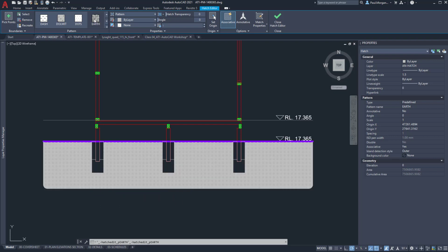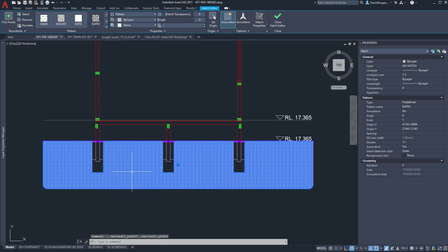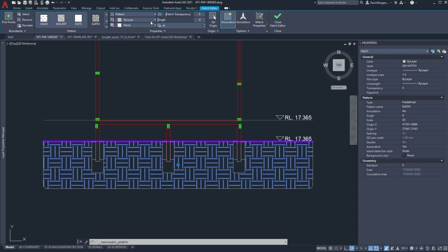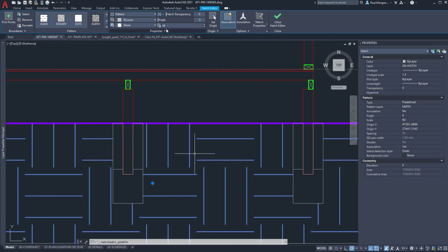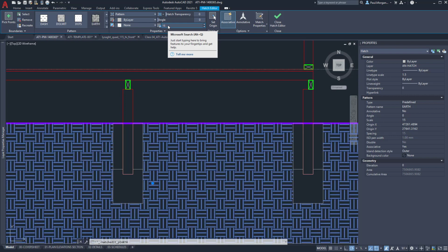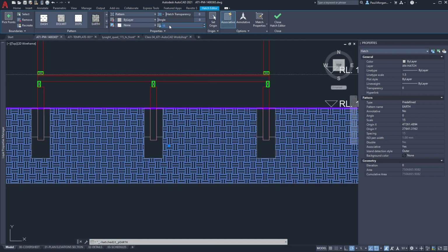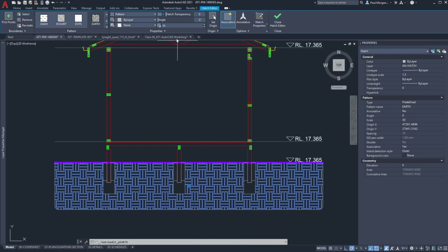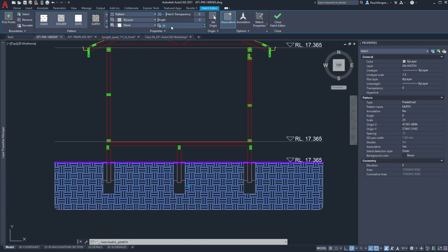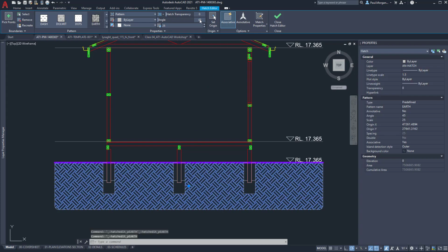So what I'm going to do now is we still have the hatch pattern. I've clicked on this hatch, I've selected it. It is the earth hatch, but there's a couple of things we need to change. One is the angle. I'm going to change this to 45 degrees. Whoop, and maybe I'll change it to 90. No. Ah, sorry, I'm changing the size. That's my bad. I'm going to change the size to say a bit bigger than that, maybe 30. Yeah, 30 looks all right. Maybe 25. Yep, and I'll change the angle to 45 degrees.